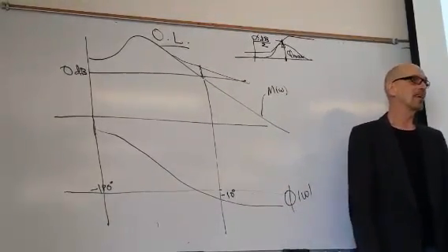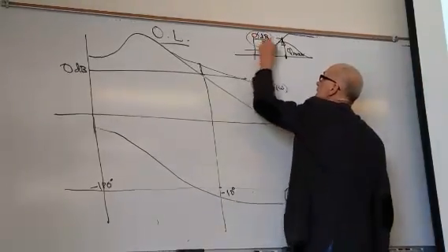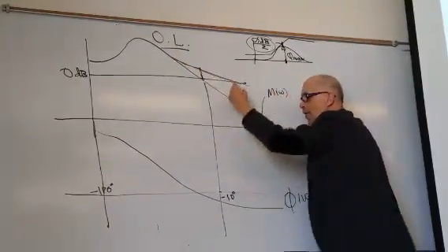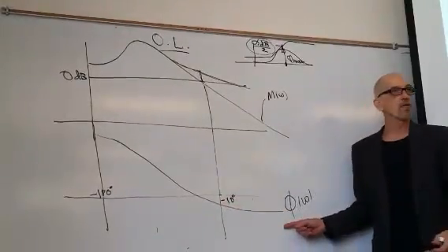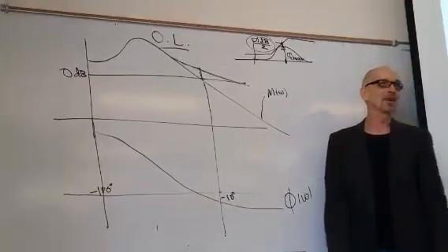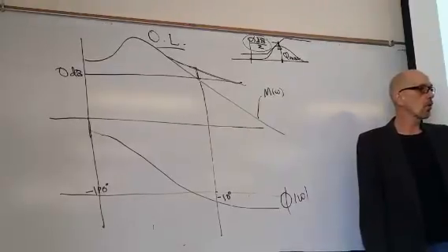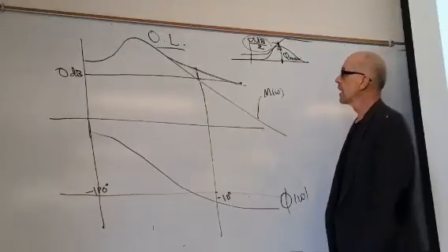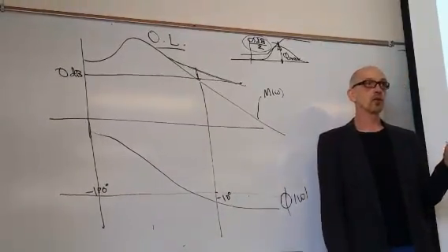So it's moved, right? So what you have to do is acknowledge that this is going to happen, and then say, well, I think it's going to happen somewhere over here, and this phase is going to be going down further. Now, if the phase goes back up, well, heck then, you're in better shape. But usually phase keeps dropping over frequency. So what you do is you say, okay, I want 40 degrees plus 5. That's a 5 degree cushion, right?